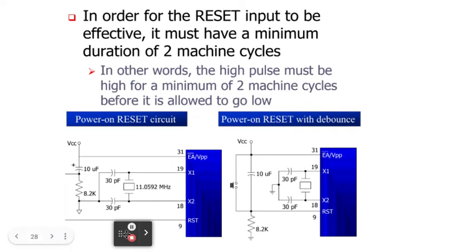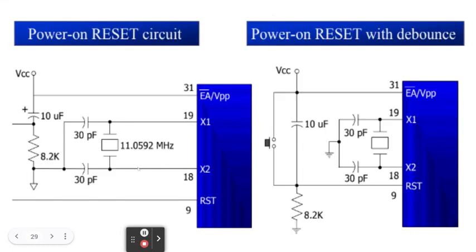And this is the figure of how you will connect the Xtal2 and Xtal1. And as you can see here, pin number 18 and 19, as I have mentioned before, are connected to a crystal quartz oscillator. And here, we're using an 11.0592 megahertz oscillator.